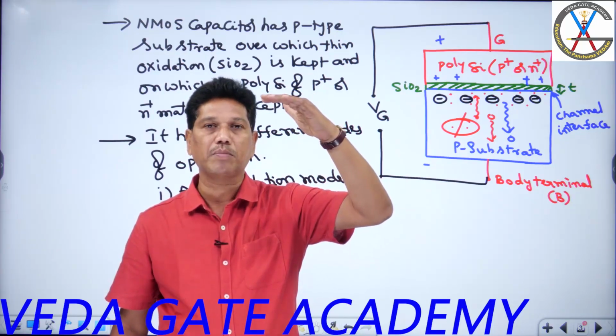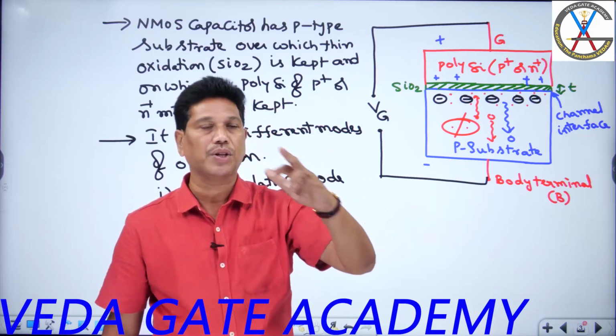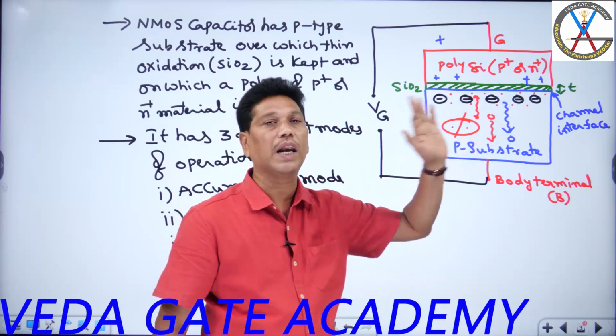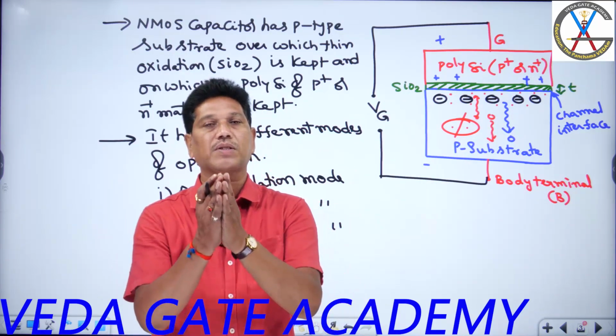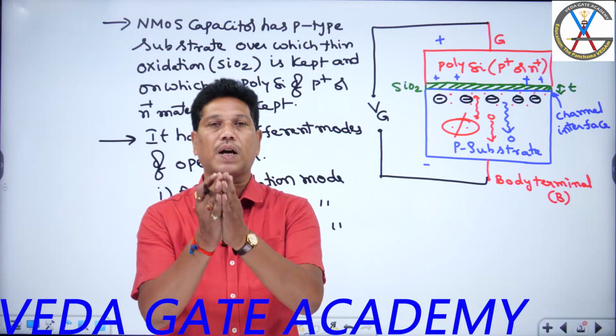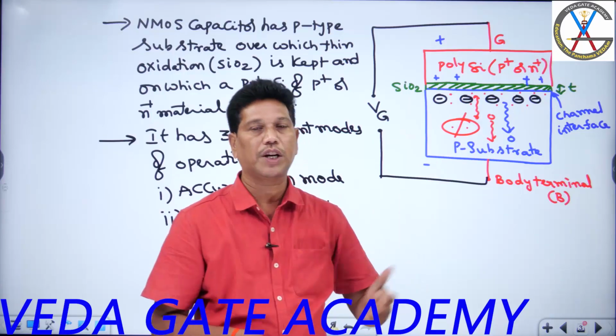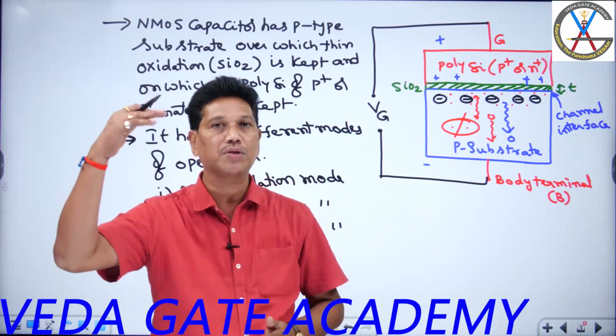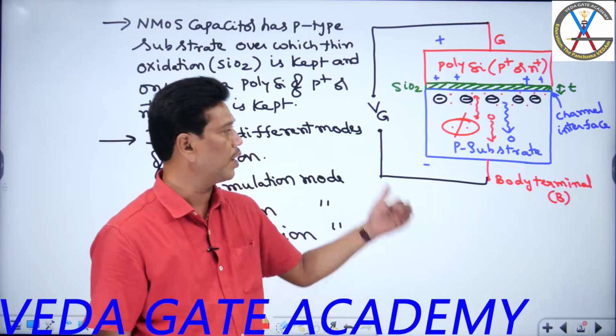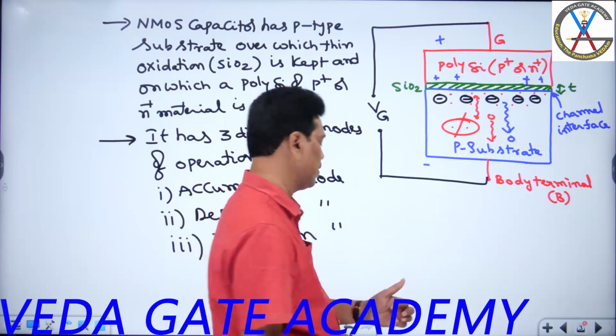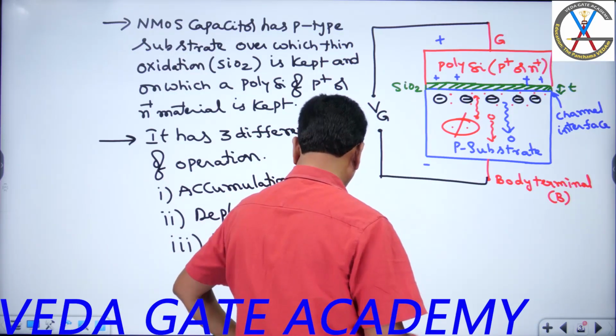Once the inversion layer becomes stronger, the added barrier effect is completely nullified. Once the barrier effect is completely nullified, the capacitance is again determined by only the oxide region, such that the capacitance again becomes maximum and constant like the accumulation mode. That's the inversion mode, you can call. Come on, students, I will go on and just clear this.